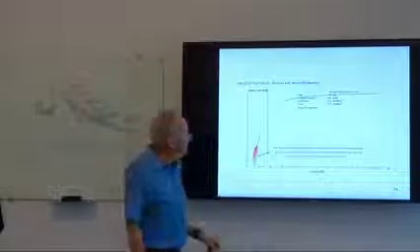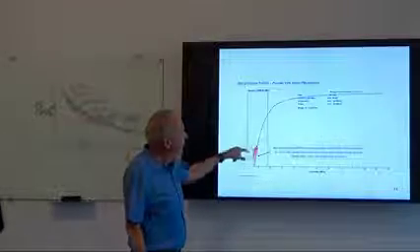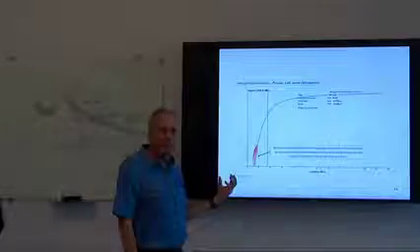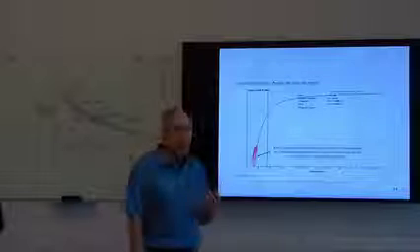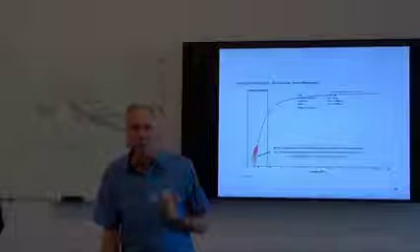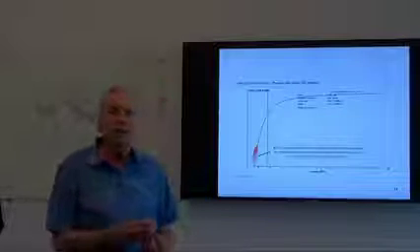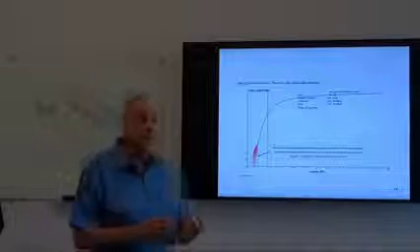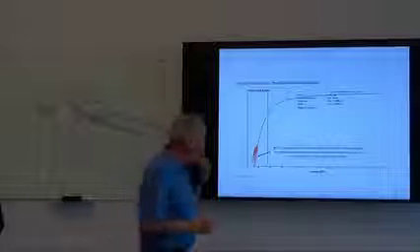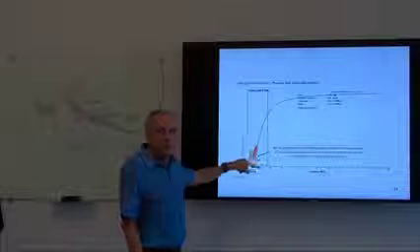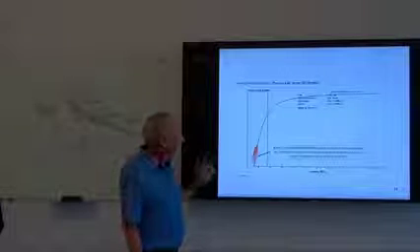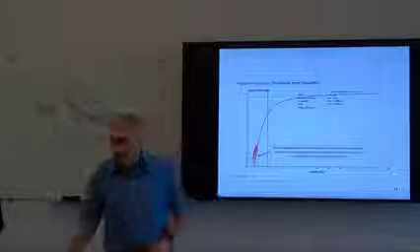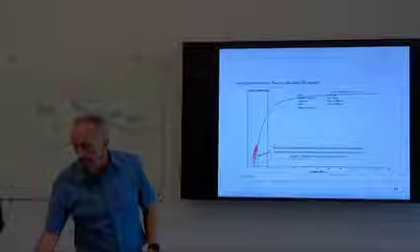So in this example, there was really no pumping effect because the gas velocity was too low. The gas in our pneumatic system was not sufficient to drive the plunger or push the plunger or fly the plunger so that it could lift the liquid. And so we struggle with our plunger down deep. And we might have to think about this well in a very different way.